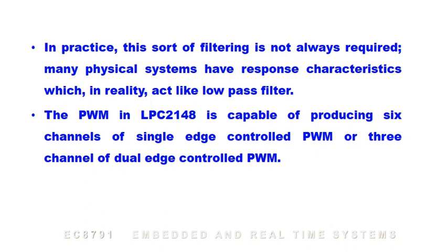The pulse width modulation in the LPC 2148 low power consumption microcontroller is capable of producing 6 channels of single edge controlled pulse width modulation or 3 channels of dual edge controlled PWM.